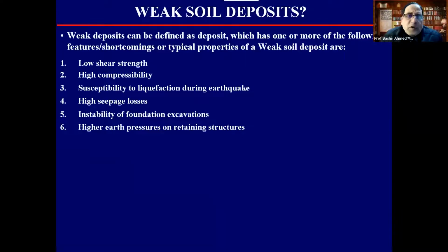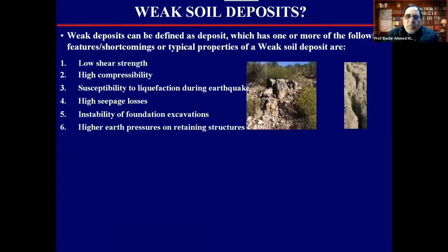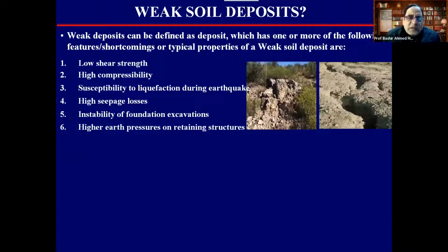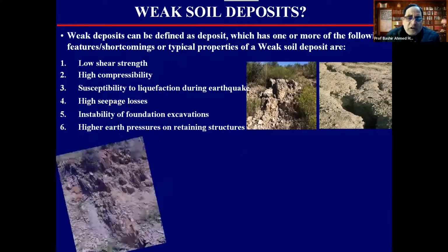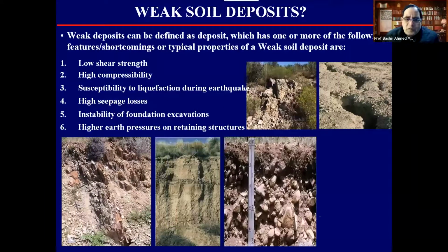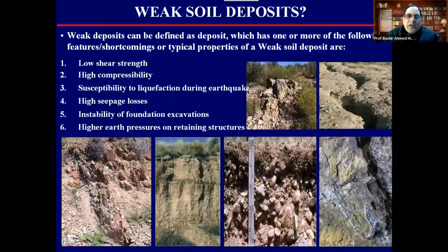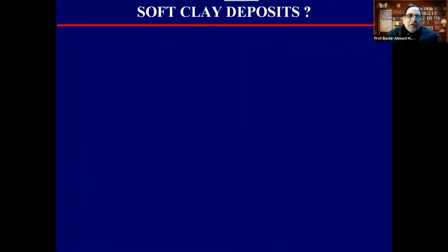Now, some properties of weak soil deposits: they have very low shear strength, high compressibility, more settlement, they can liquefy, there can be high seepage losses, foundation instability, and higher pressures on retaining walls if proper fill material is not used. They need to be modified or treated.